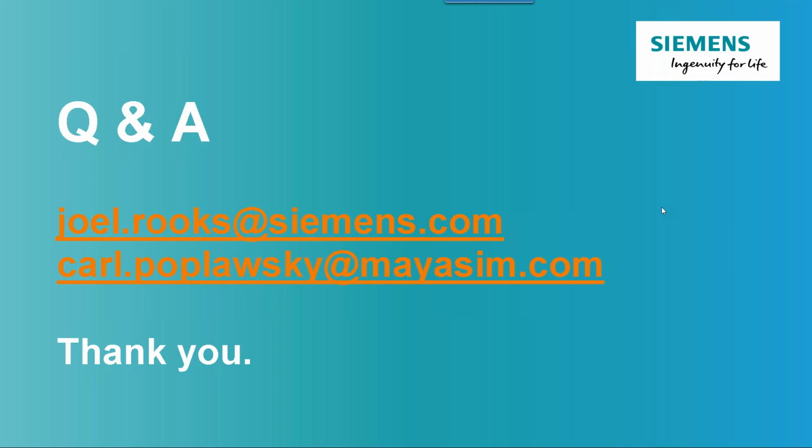So yes, a little bit like I did for the heat loads, you can do the same for all the other values. You can manually change them or manually enter them. Also, you still have access to the catalog in Simcenter. I didn't show that in the demo, but if you create a brand new PCB component, you can go and pick a component from the catalog, and Simcenter will fill out the form or the simulation object for you based on what's in the catalog as well.